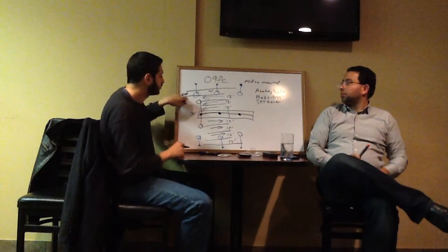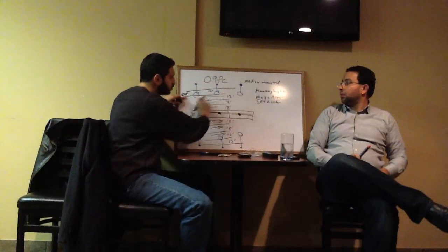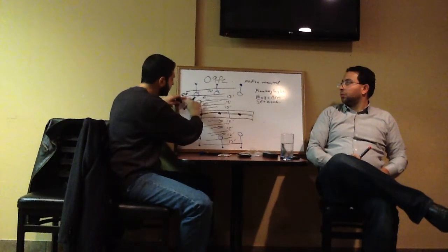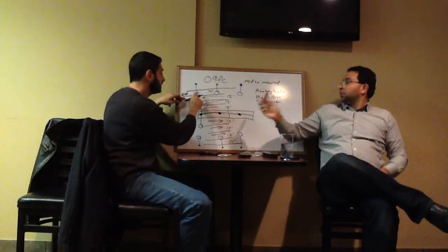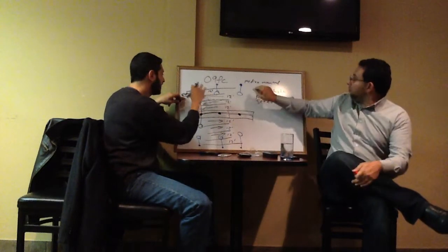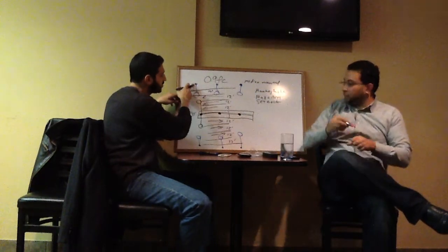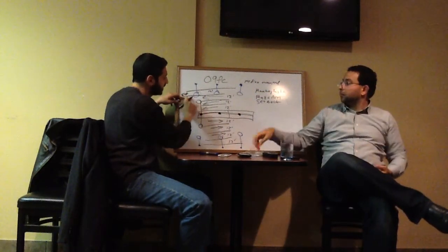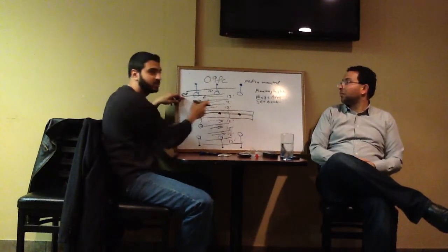This is the edge of the traveled pavement, because shoulders are not really supposed to be ridden on, so your traffic is going to be mainly here. So you want your actual luminaire behind the edge of pavement. The setback is how far the pole is behind the edge of pavement. So if my mast arm is 15, I would want my setback to at least be 15.